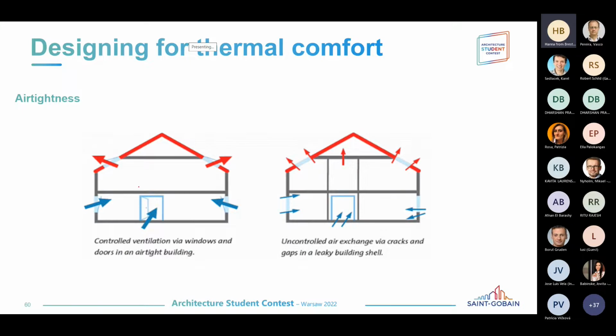Airtightness. Then the second step of the airtightness is the fact that, as I was mentioning, this has to do also with the quality of the air inside. If I'm bringing the air inside through a ventilation system, then I can say that I'm going to use some kind of filter for particles, for pollen and so on, and I will already remove a lot of the harmful things which are mostly in the cities, in the area.